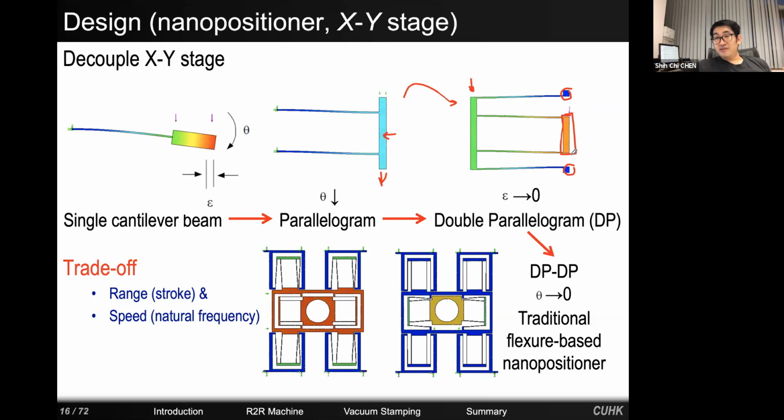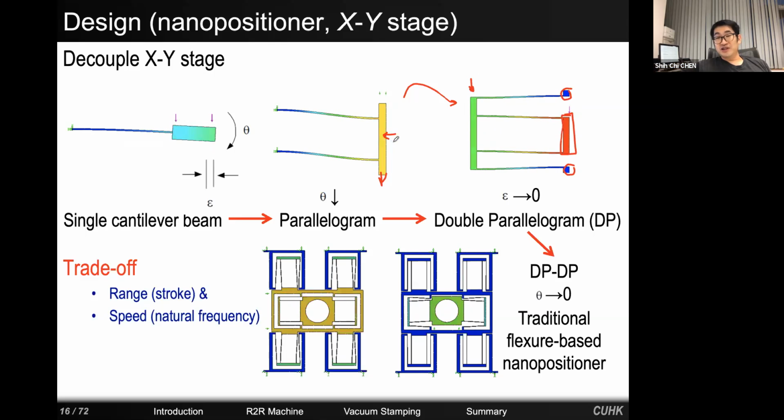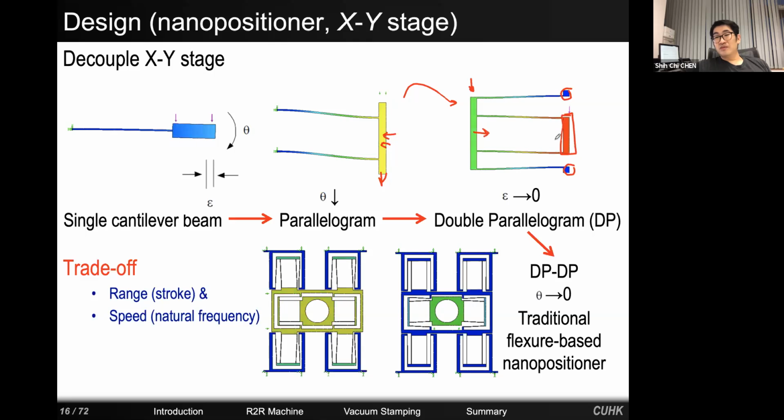So as the main moving stage moves, the secondary stage will move half the displacement. So for large displacement, these will move inward, right? Like I mentioned. So this would move inward, but the main stage would not move laterally. Okay. And this also allows large displacement.